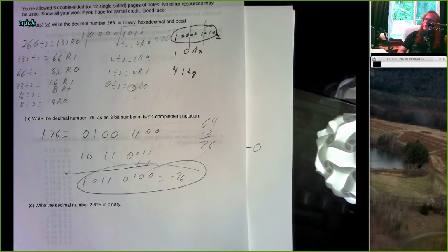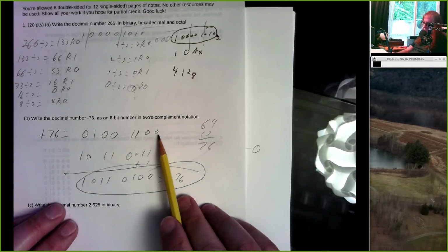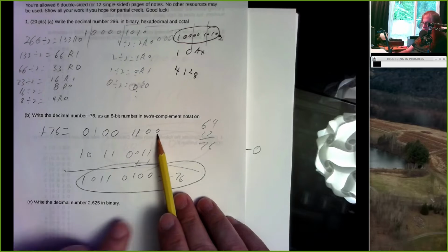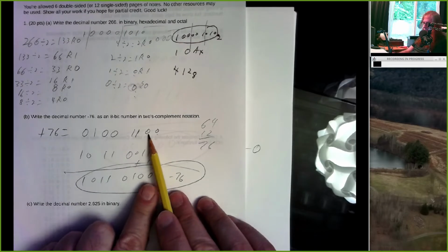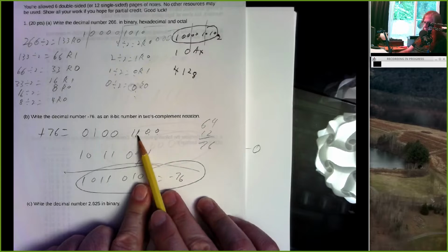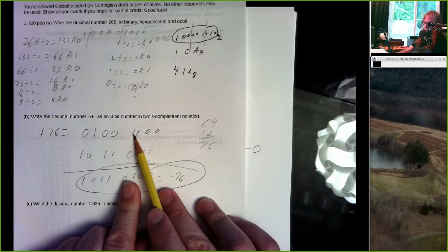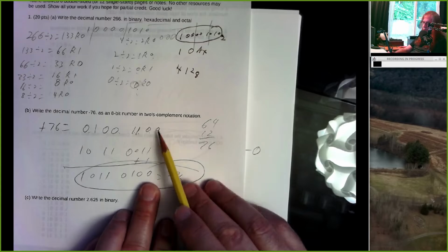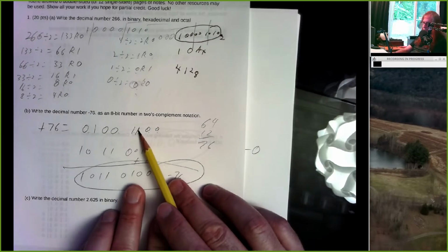Now there's a trick you can do for 2's complement, which is, if you want to toggle all of these bits and add 1, start from the right. If you have a 0, keep that 0 and move over. If you have a 0, keep that 0 and move over. If you have a 1, keep that 1. But now, for the rest of the number, just toggle the bits. And that's a shorthand way of saying complement all the bits and add 1. If you have zeros, starting from the right, keep them until you get to a 1. Keep that first 1 and then toggle everything else.